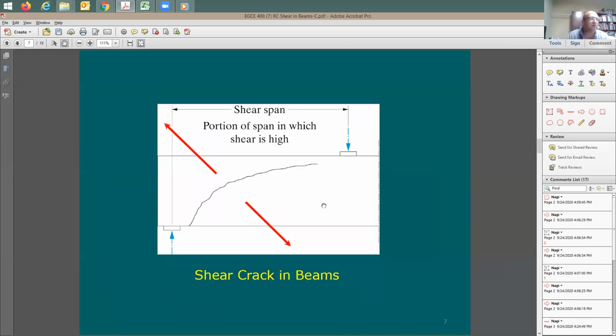So for example, I'm going to go back here. Let's say that I start to put some vertical rebars here, and these vertical rebars are what we call ties or stirrups, right? I'm going to put them like this. If you just put some rebars like this and you didn't hook them to any reinforcing on top and bottom, now once this wants to open, this rebar here, you can just slip it. You can just pull it out of this concrete piece. Nothing is going to stop it unless you hook it to something.